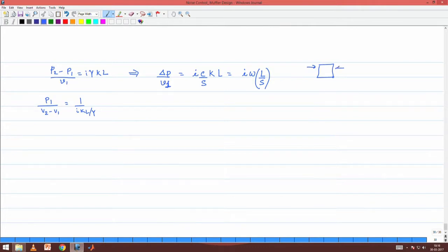You had the impedance, when you did the impedance of the mass element, you said that the forces on the two sides need not be the same, right, and therefore, you said that delta F by V is j omega m. This is i omega m, right. So, this looks exactly of the same form as the equation of the mass element or that of the inductor in electrical circuit analogy, right. What about the second equation?